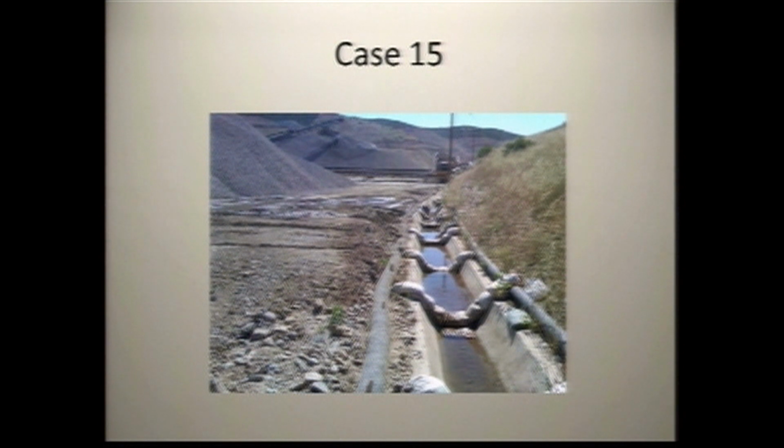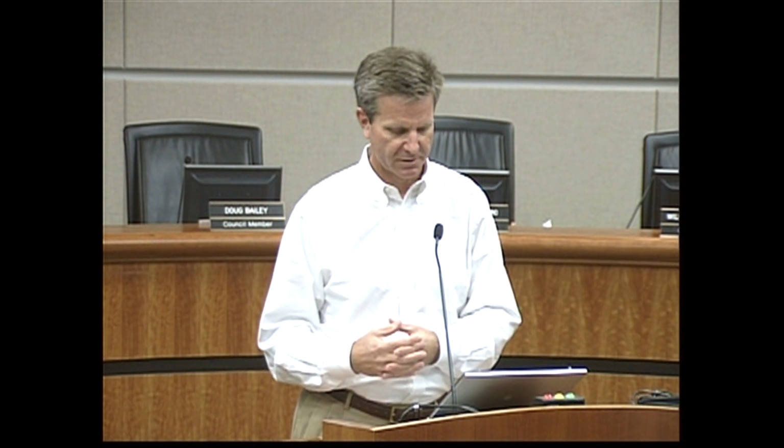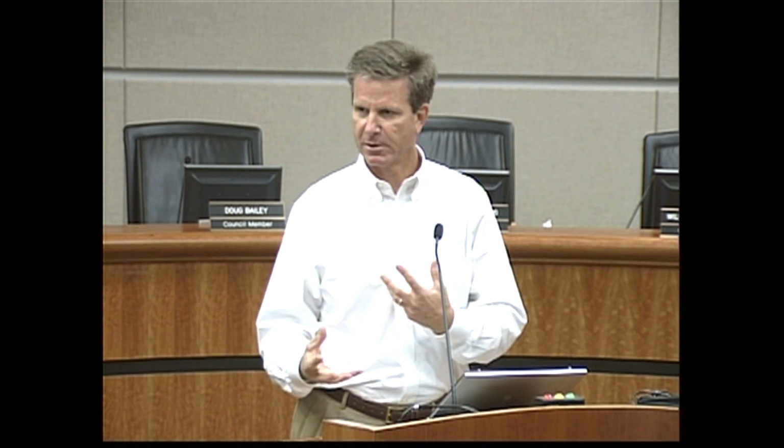So your poor NPDES coordinator at your city is going to get called out and have to start some sort of investigation of why there's dry weather flow at a storm drain outlet that's never had it before, and it probably has sanitary quality problems and stuff. This was a job that was constructing a roller compacted concrete dam, and they were using water to cool the gravel pile because the aggregate has to be cooled to go into the RCC mix.